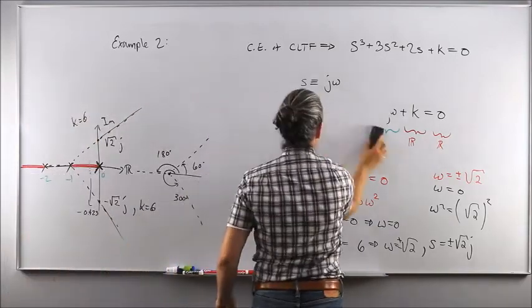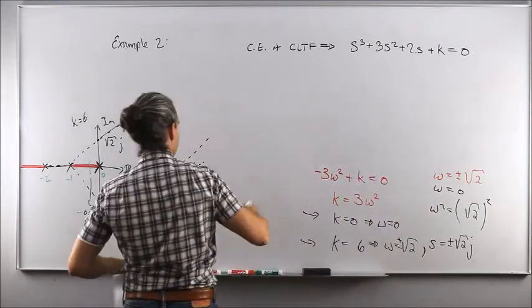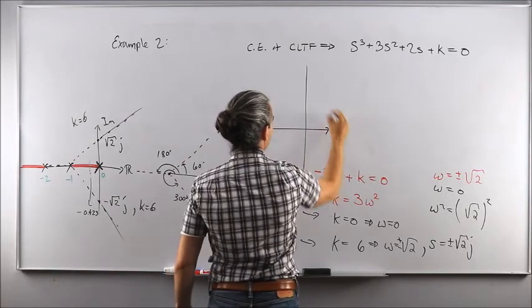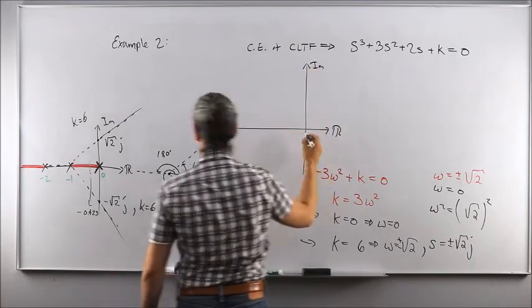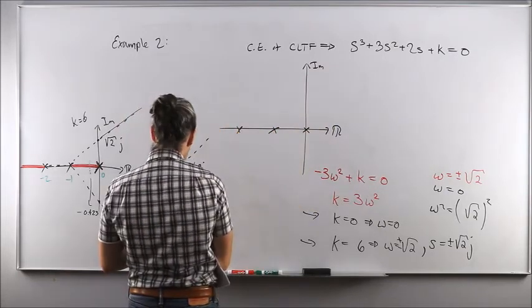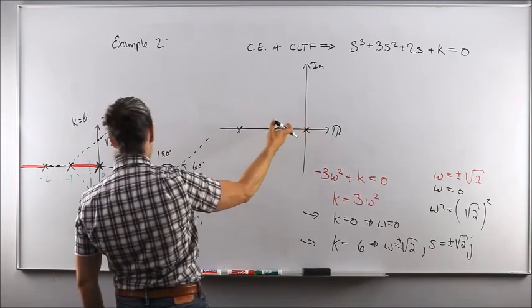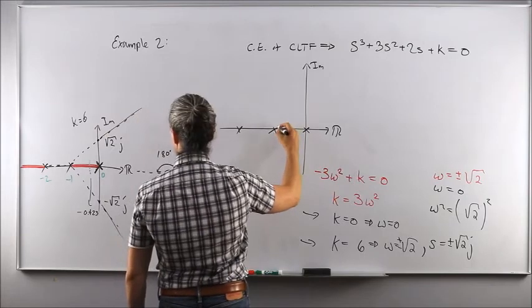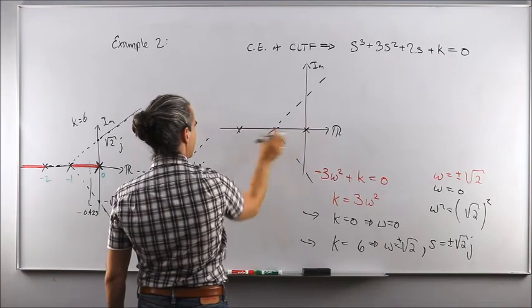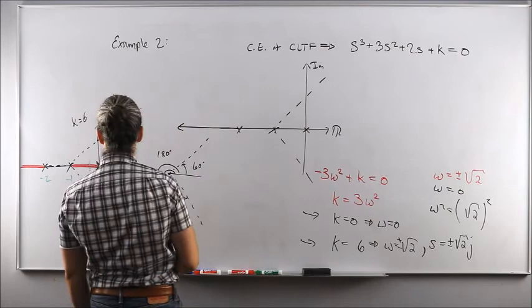So altogether, you could just redraw the entire root locus a little bit neater based on everything you've obtained so far. K equals 0, that's where you are. Keep increasing your gain, and you now visualize the closed loop poles as opposed to the open loop poles at k equals 0. What's going to happen is that because you have two asymptotes here, and that the root locus exists here and over there, it means that this one will just fly on its own towards the left.